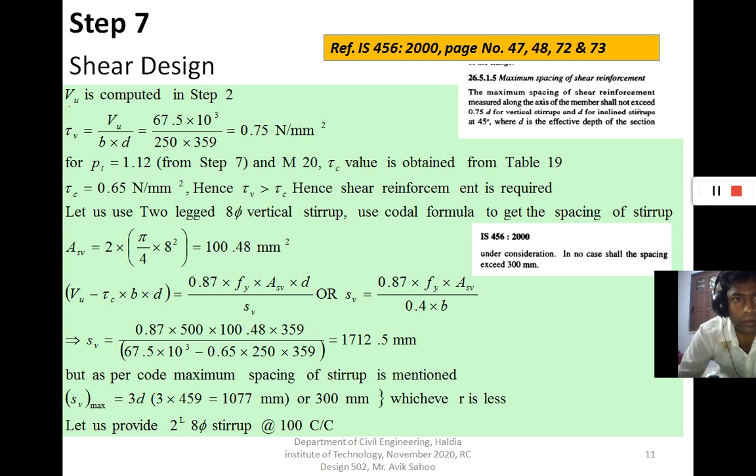So first you compute the shear forces, which is tau v is equal to Vu by bd. This expression is given in page 72 and 73.